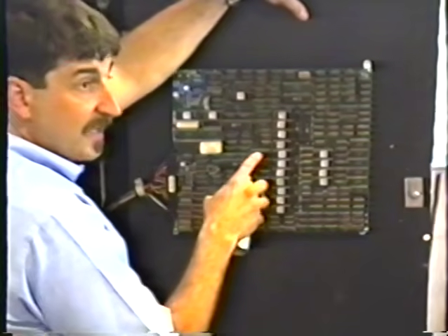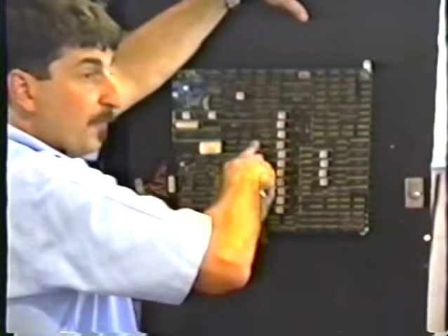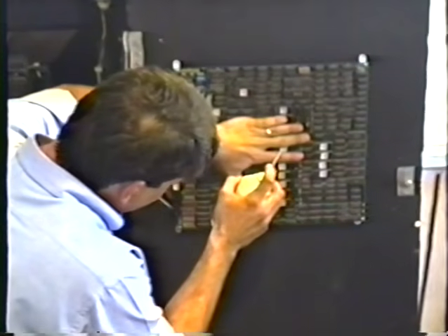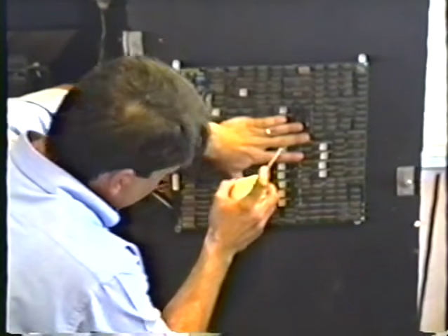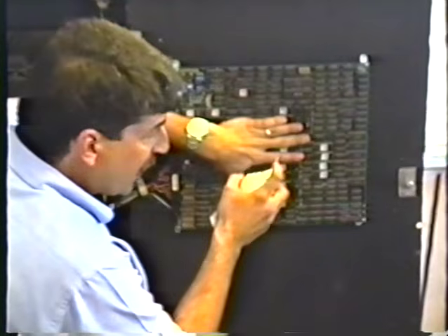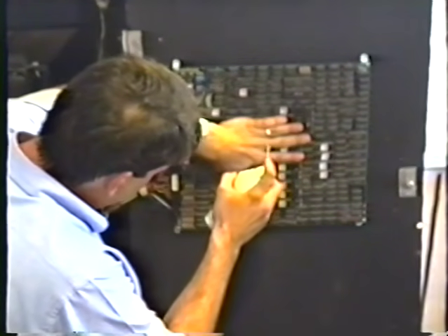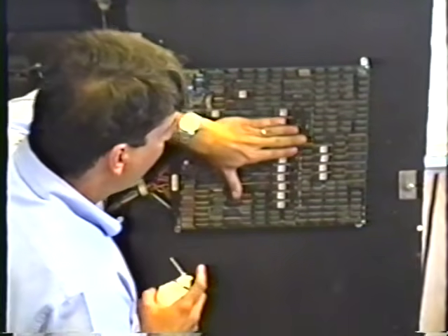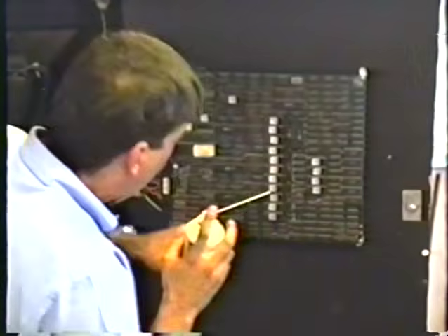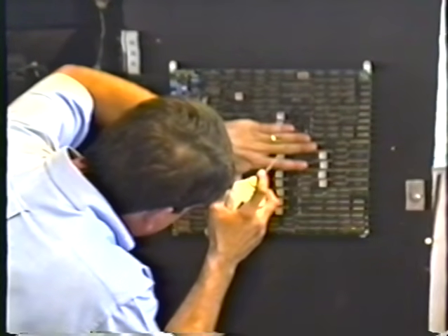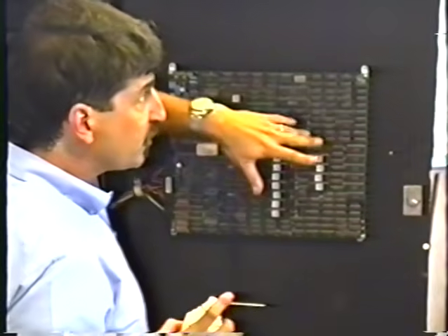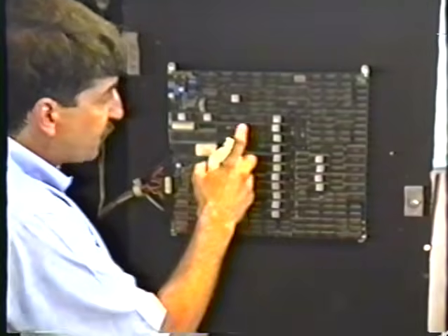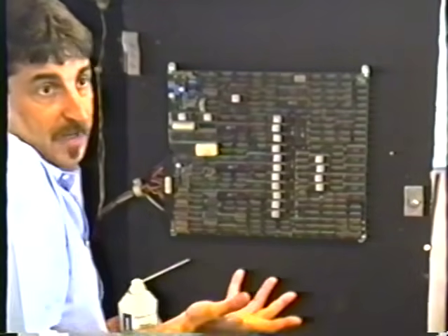Now, you may have found the right IC, you may have not found the right IC. Heat it up again with the hair dryer. Temperature cycle it many times. What I often do is I'll cover up the adjacent chips with my fingers like this, barely hit it. While you're up here, if you've got a wart or something, just go ahead and freeze that baby right off. Just hit it. Okay, problem goes away. Get the hair dryer out. Heat it up. Oh, problem occurs. Make sure that you are just hitting that one chip that you think is bad. Temperature cycle it 5 times to make sure that that's the chip, because it's real easy to overspray and hit an adjacent chip and cool that one off simultaneously.